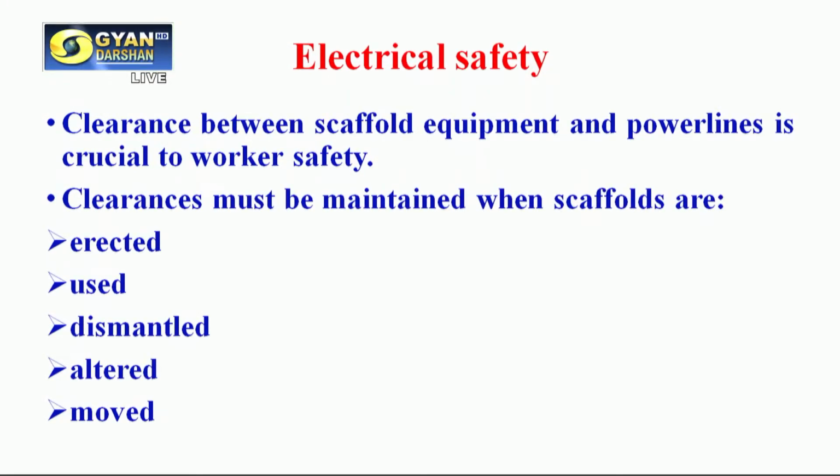So what can we do for electrical safety? Proper clearance between the scaffold equipment and power lines should be there. Clearance must be maintained when scaffolds are erected, used, dismantled, altered or moved. So we have to be very careful while doing all these things. If we keep all these things in mind, we can avoid the electrical hazards.